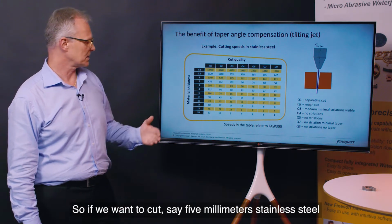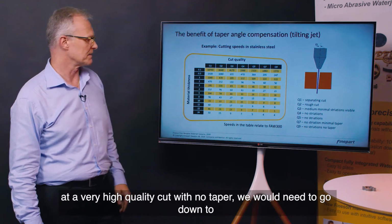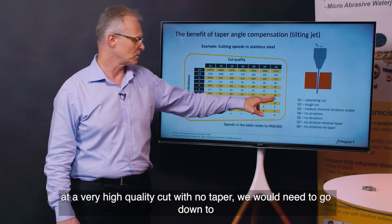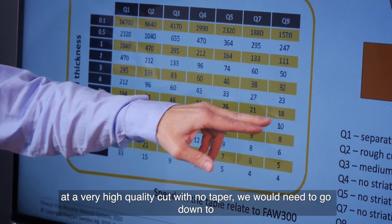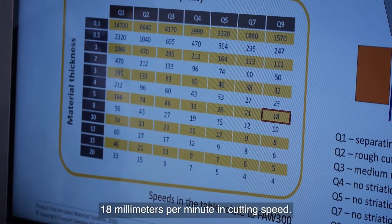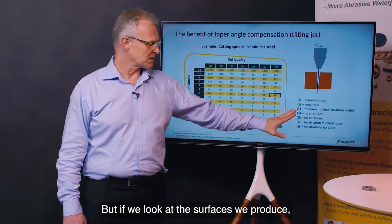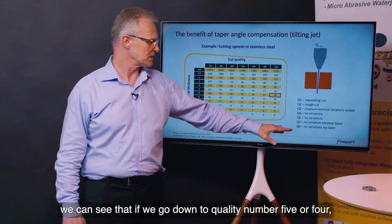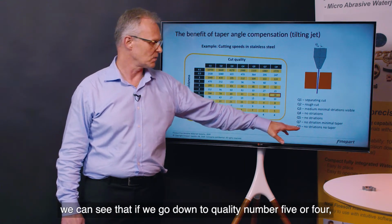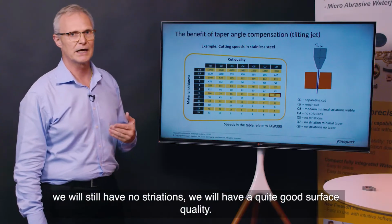So if we want to cut, say, 5mm stainless steel at a very high quality cut with no taper, we will need to go down to 18 millimeters per minute in cutting speed. But if we look at the surfaces we produce, we can see that if we go down to quality number 5 or 4, we will still have no striation.